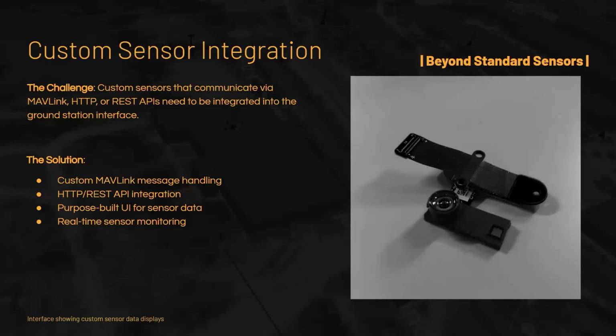Then you'd have to basically hit it through the ground control station, or you would need to maybe add a driver in PX4 or ArduPilot to support it. But yeah, this one is kind of specific to whatever hardware you're actually trying to add support for. And sometimes the answer is not a QGC modification for this, but other times, if you want to display some certain data, or there's certain data that's not available that can be, then custom sensor integration might be the answer. And it might involve both a firmware modification and a ground control station modification in many cases.